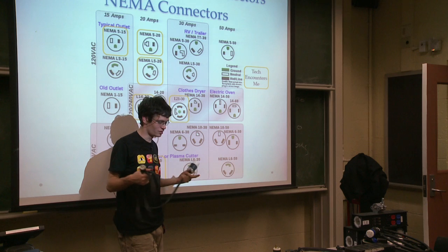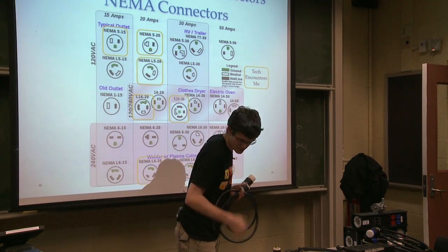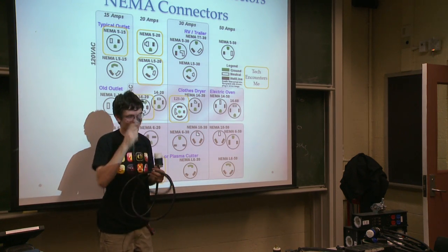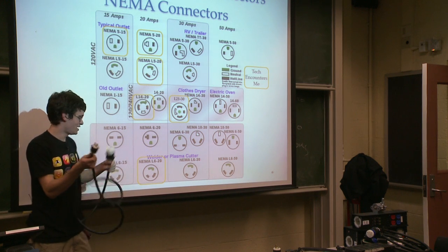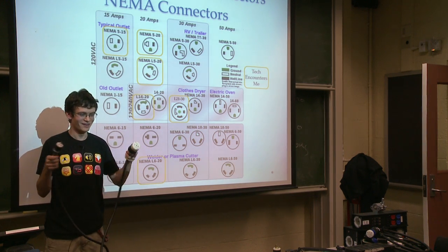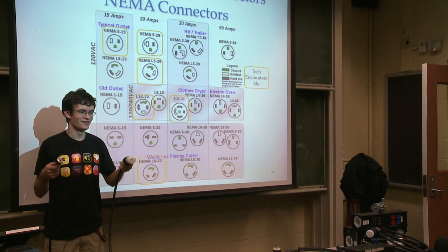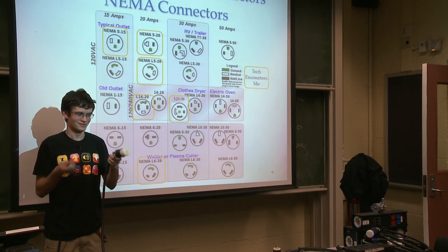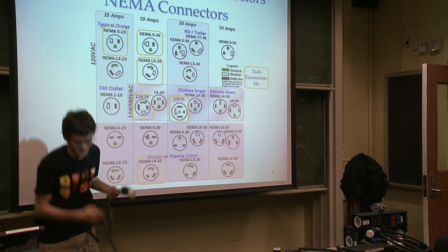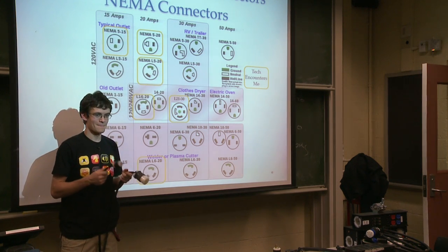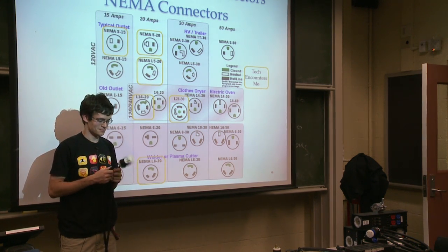Okay. Our last cheater, I believe. Yeah, it's our last cheater. Is this guy. It is a 515 male and a 2130 female. Is this guy good, bad, or just confused? Incredibly useful. It is not the worst thing in the world. It's used for running amp tanks. Where's my 208? When there's no real power distribution.